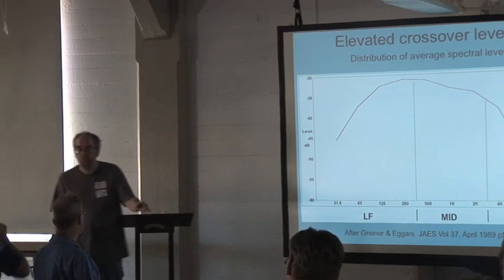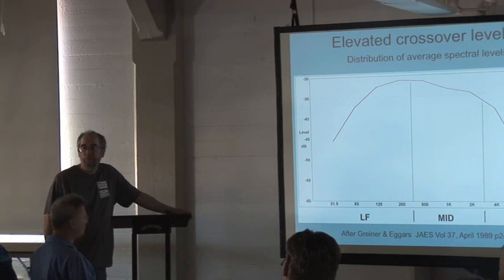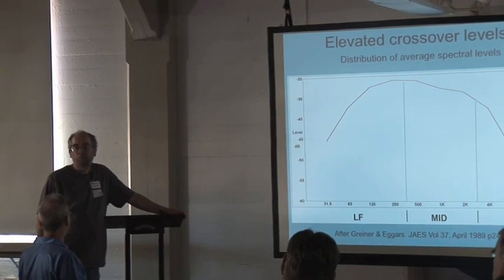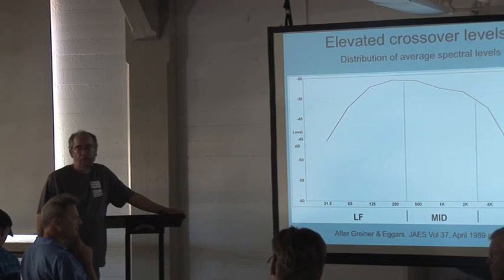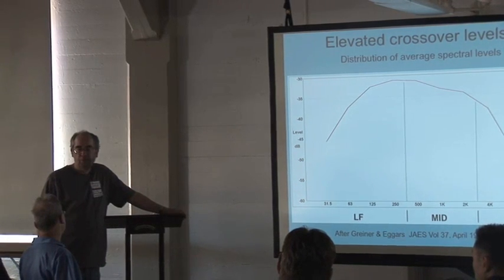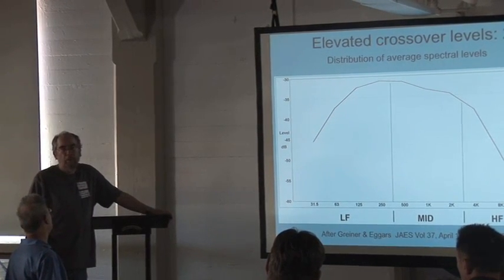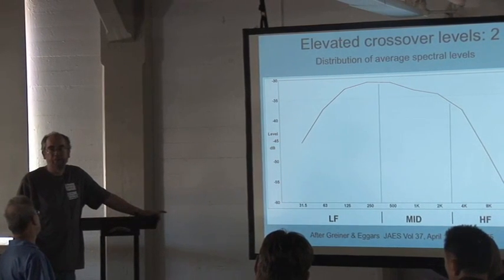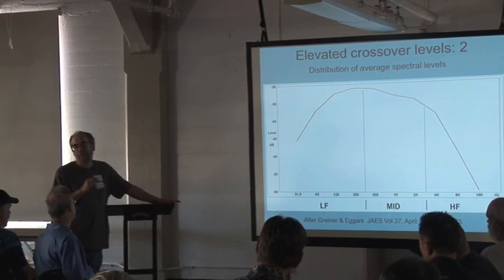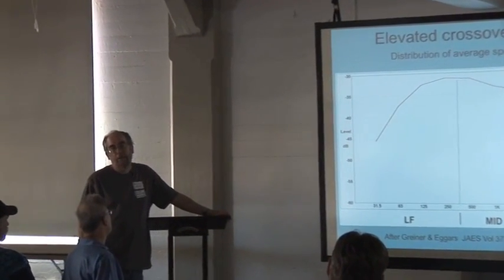As far as speaker cables running all the way from the speaker back to your crossover, do you prefer running a 3-line rather than a 2 to reduce hum and just better sound? Balanced, I think you mean. Yeah, a balanced drive to the loudspeaker? No, balanced input, to the input of the crossover, or running all the way through the whole process to the amplifier? Well, I'm not aware you can get balanced loudspeakers, unless they've got transformers in them or something. But I would certainly advocate running balanced between the active crossover and the power amp, definitely. In fact, whenever you can do it. There is every reason to do active and balanced if you can.